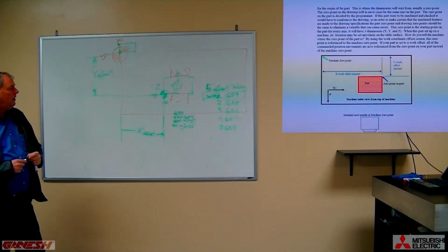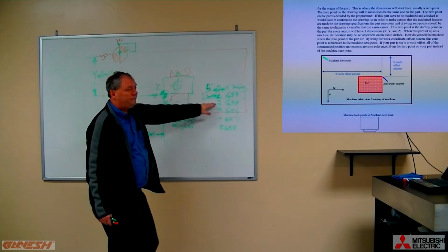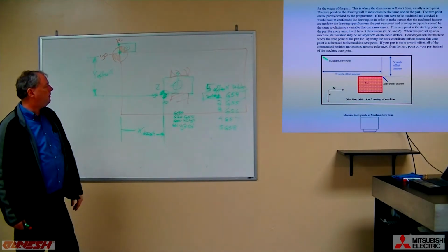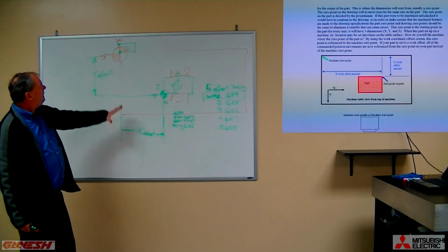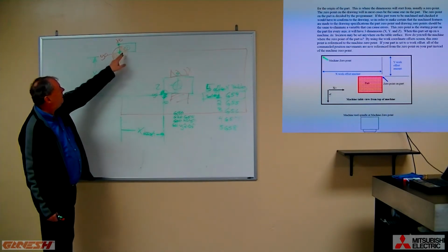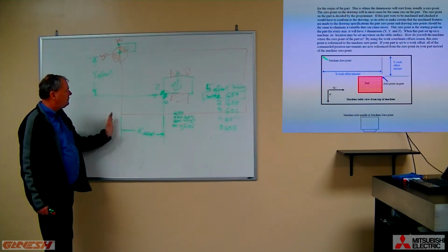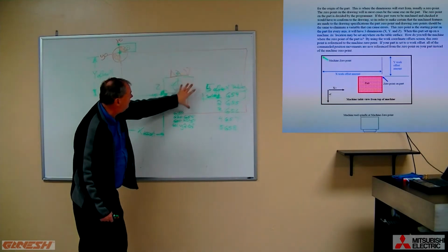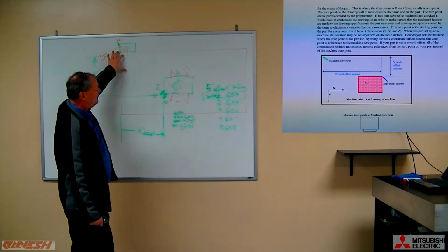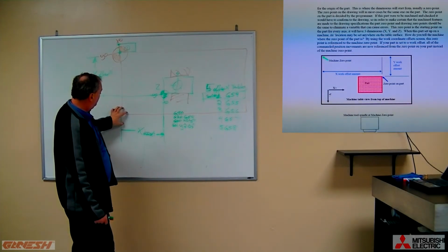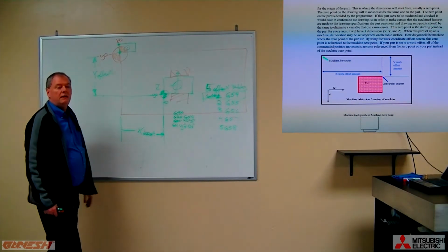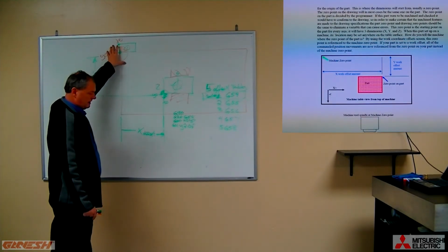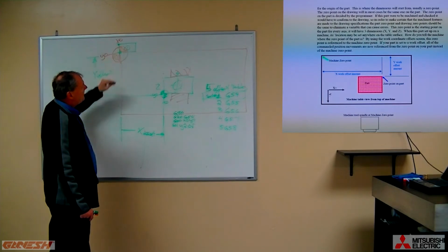Or if you've told them to load it into the G55 offset table, you would make that G55 in your part program. But you need to realize that we have to let the machine know that there are shifts between where my part actually is and where the machine thinks its 0 is. Some machines have it down here. It depends on the machine. But the machines we have on the shop floor that we've demonstrated do it from the upper left-hand corner.